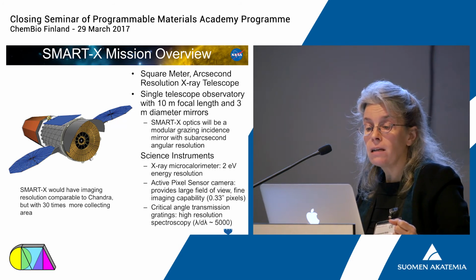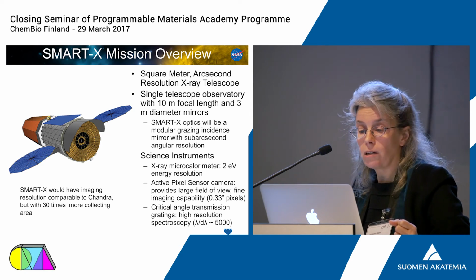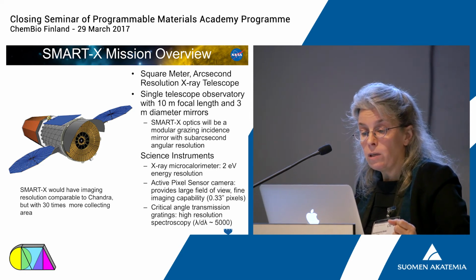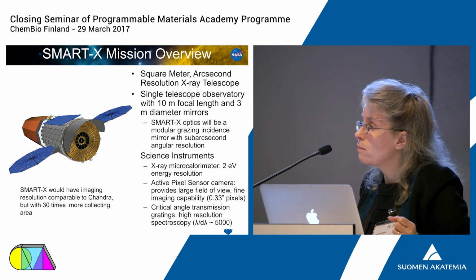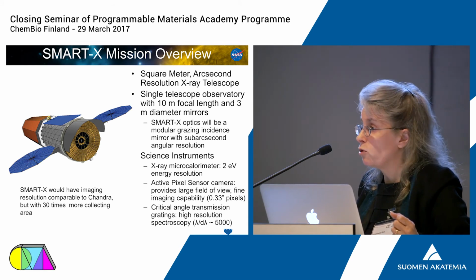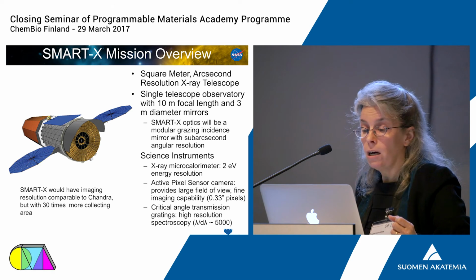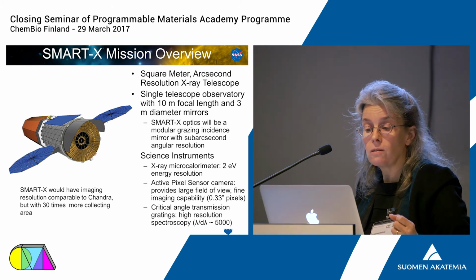If we embed magnets in that, we can use those magnets to pluck the piezoelectric elements. And we think that this device, for realistic achievable values of the piezoelectric coefficient, should give us about 3 times more power during a conventional walking motion relative to the out-of-plane devices.